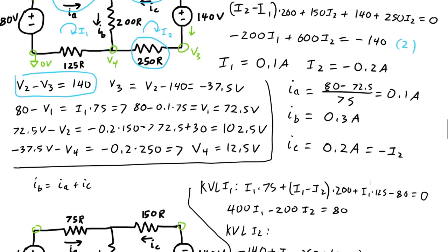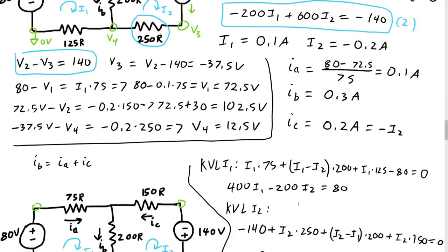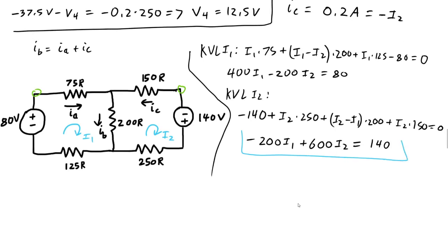So we scroll up, we can see that this second equation 2 is pretty much exactly the same as this one. The only difference is instead of minus here, it's plus. That's because we flipped the voltage source around. Anyway, use whatever your favorite way to solve linear equations is. I did this in my calculator. So I1 equals 0.38 amps and I2 equals 0.36 amps.